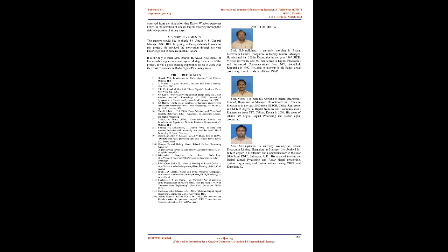PFA equals 1 times 10 to the power of -6. Number of training cells, 16. Number of guard cells, 4. Target 2 parameters. Range, 13 km. Velocity, 50 m/s. Target RCS, 1 square meter.